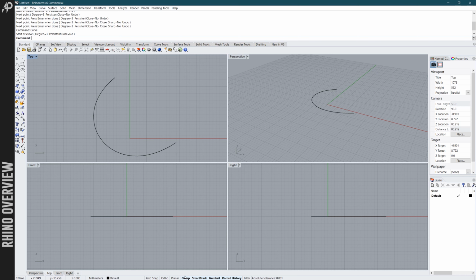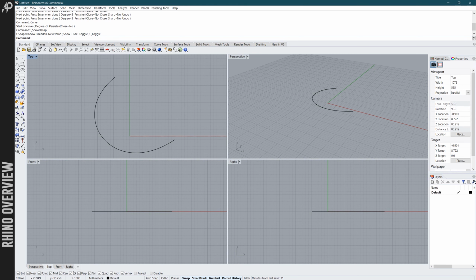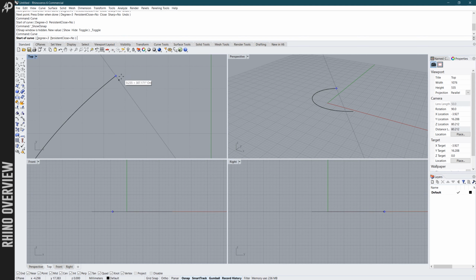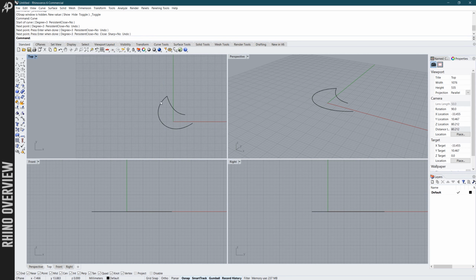You can access the snap menu down here. You just click it. You can see all the elements that I can potentially snap to. We can leave all of them on, it doesn't matter for our use. It might happen that you need to turn it off sometimes. For instance, if we wanted to draw a point really close to the end of the first curve but not coincident, then it keeps snapping constantly. So you will just need to turn it off, and now it's all okay. So it was the osnap function. You can just draw a second curve.